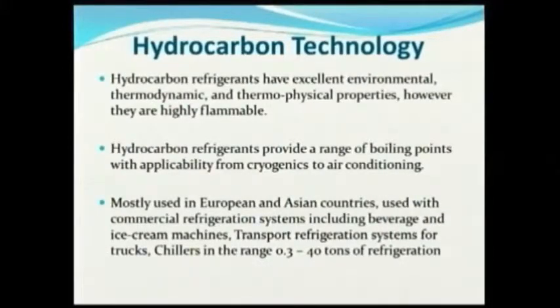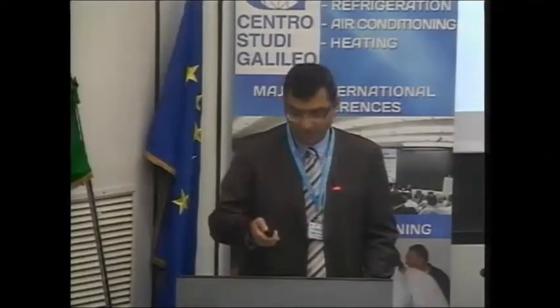They have a very large range of boiling points, so the application is really wide, from cryogenic to air conditioning systems. So this is a very good refrigerant to be looked at, mostly used in European and Asian countries, and used in commercial refrigeration systems, beverage and ice machines, and so on, from 0.3 to 40 tons. So this refrigerant is a good refrigerant, except for this flammability issue.